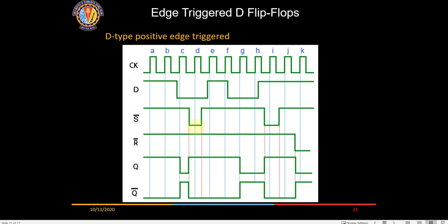During that time, it doesn't wait for a clock signal. The moment set or reset is applied, the output would change. This set and reset is the highest priority, which will straight away do the reset and set in the output. It will not wait for the clock. Is it okay with everybody? Anybody has a doubt? Otherwise, if you can say yes or no, it will be easy for me to move forward.